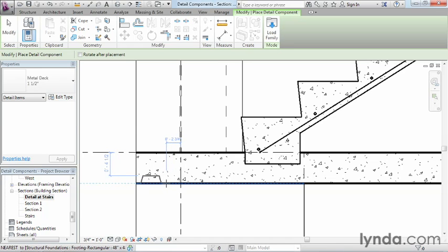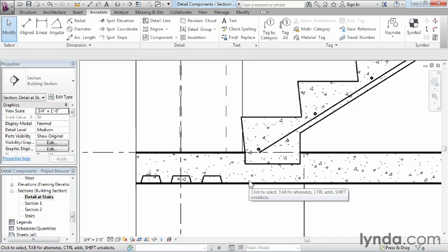So next, we can just move over here and click once. Keep moving over, click again. You'll almost feel them snap into place really once they get to the end of another one. So you can do even spacing, but there's a better way to be evenly spacing this metal deck going all the way across. In order to be able to do that, there's actually another command which is directly related to this command that we're currently in.